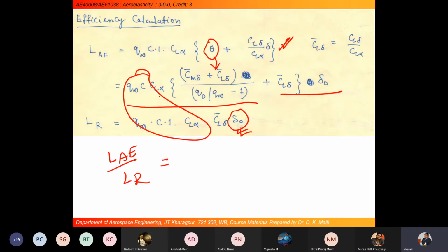That means, we will be calculating the aeroelastic lift, due to the aeroelastic phenomenon, whatever correction there is in the lift force distribution, and then dividing by the lift we would get if the structure is considered ideal, infinitely rigid, with no additional deformation due to the flexibility of the structure. That I am defining as L_R, the rigid lift.